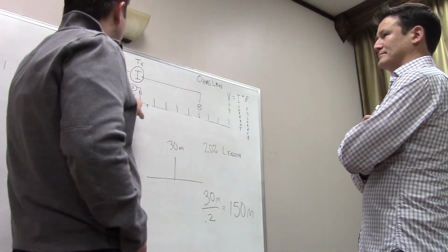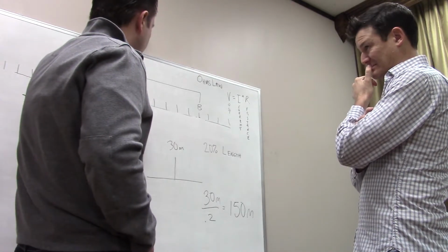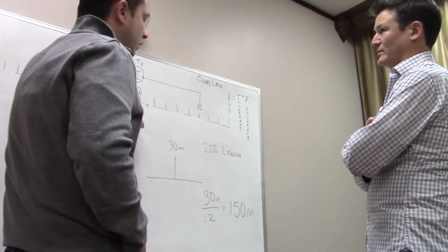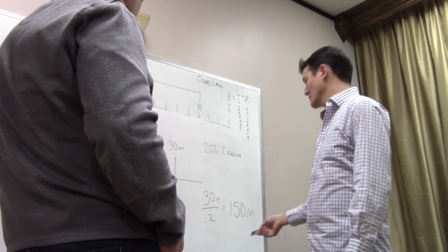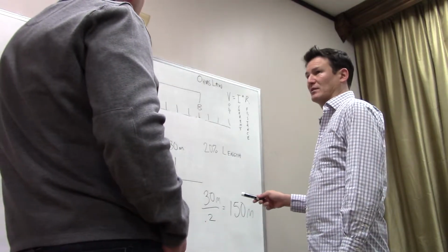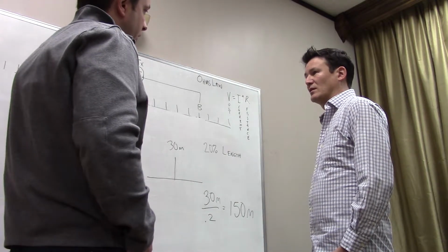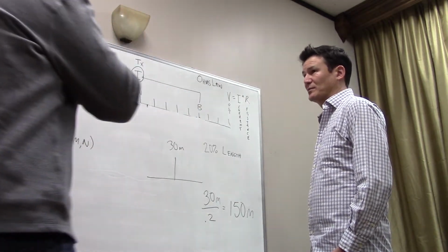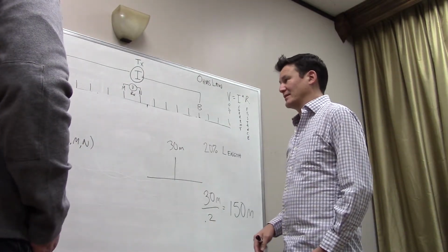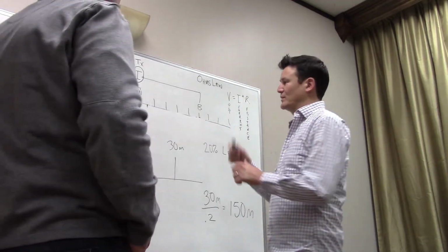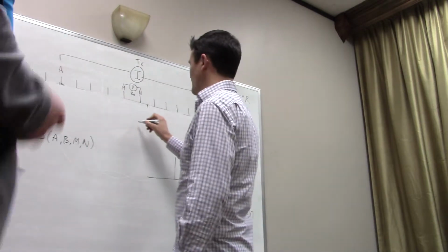Mm-hmm. And then the receivers, depending on how wide apart those are, that would give you the resolution. Yes. Okay. So you have to apply more electrodes, more of these positions, in order to get better resolution with depth. But if you put them too close, all you're getting is the surface rather than the depth. Well, you're always going to get the depth also, but the resolution is mostly improved in the near surface. So the way that we could divide this 30 meters, so 20% up, and let's say about 3 intervals, okay?